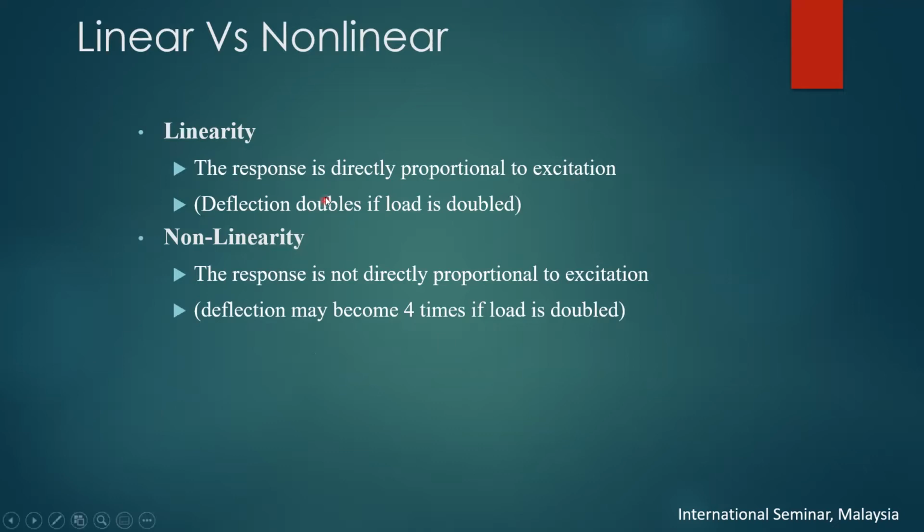Now, linearity is when the response is directly proportional to the excitation. Nonlinearity is when the response is not directly proportional. So the deflection can double if the load is doubled. If I put 100 kilonewton, for example, let me draw this building. Imagine this is a building. We have 2 floors, and we have the support here.